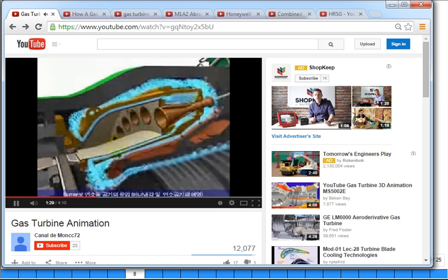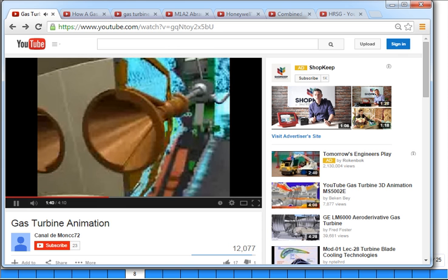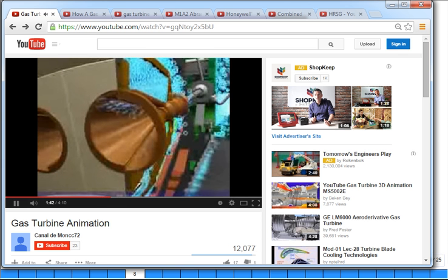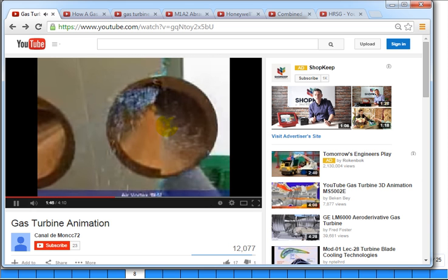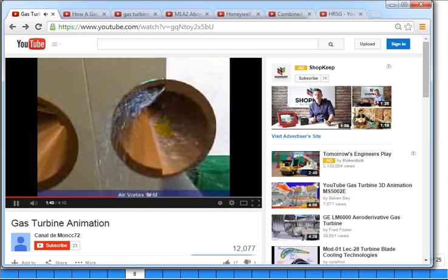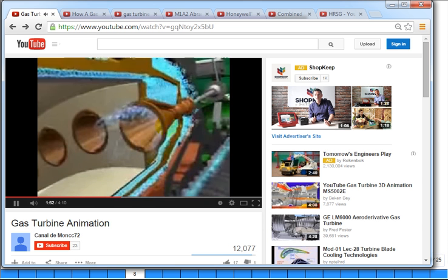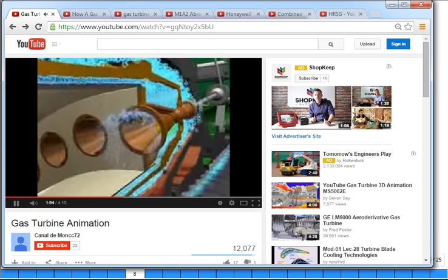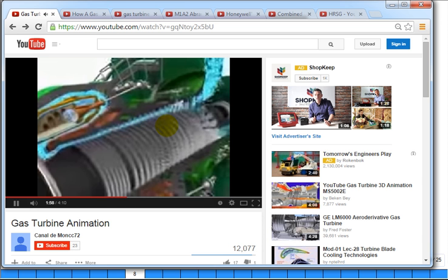One of the reasons I wanted to show this one especially is when he turns, he'll orient it. You can see what they've done right here. They like swirl in combustion. Swirl, good mixing, air-fuel mix. This is just one concept of the design. And a lot of that mass flow of the air doesn't combust. It would be too hot.